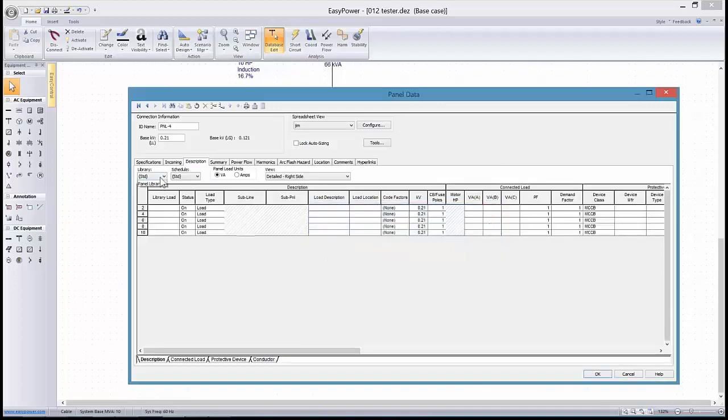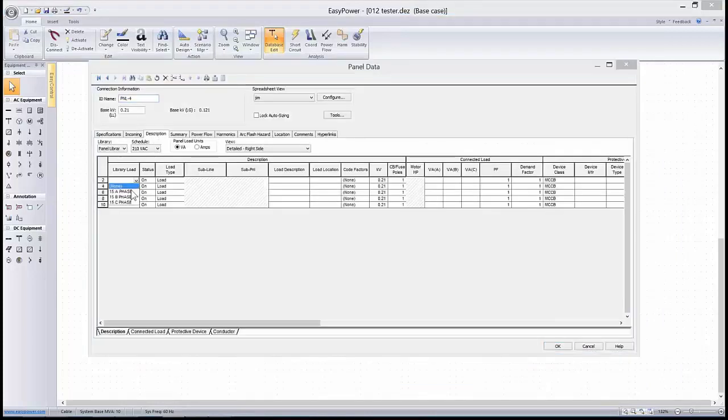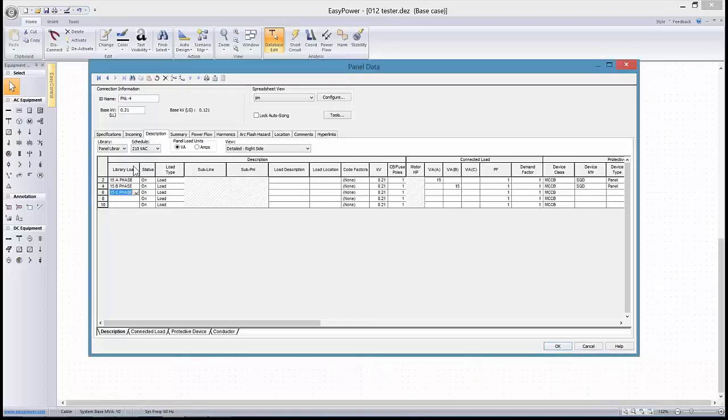Now the same kind of thing is I may set up a library load for 210 volt systems. So I'm going to link that and then reopen it. And as I go in and bring in the loads here, we could have a 15 amp A, 15 amp B, and a 15 amp C. Although I think this would only be a 2-phase coming off of 2-phase to ground. So let's take this one out. Each of these are single-phase loads, but they're going across a 210 volt supply. All righty, gotta get rid of this one.